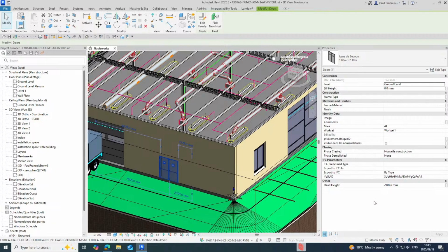Interesting one was raised recently. I just had a look at it actually online. Jeremy Dummick discussed it. He's the building coder, and the question that was asked was around this IFC GUID, and saying that if you do an IFC export, then one of the options is for you to create this IFC GUID. You can actually control this IFC GUID from here. So it's read and writable, so you can actually type something in there and overwrite it. And it's my intention to replace this with the Revit ID.